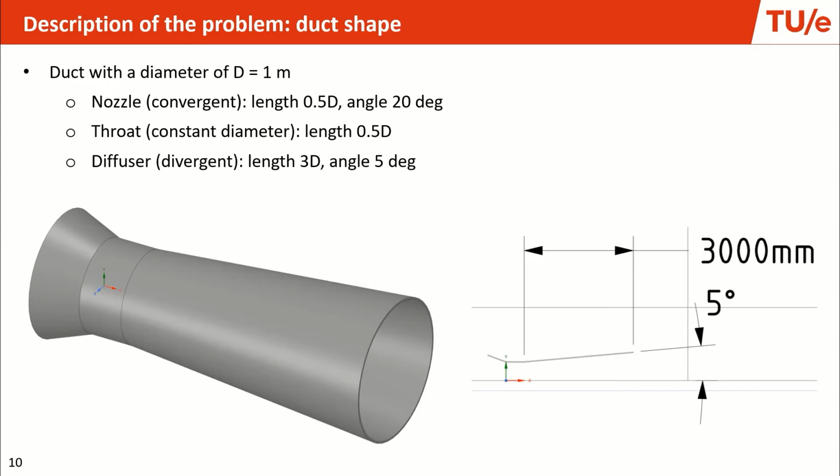In this tutorial, we're going to simulate this duct using 2D axisymmetric simulations. Therefore, we'll create a 2D domain, and inside the simulation software, we're going to define it as a 2D axisymmetric case.